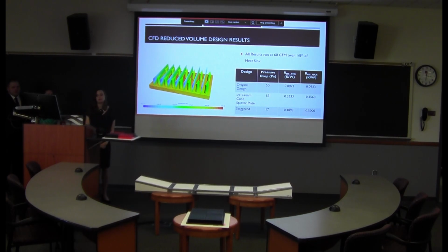Moving on to some of our results from the reduced volume designs. Again, all of these simulations were run at 60 CFM over an 8th of the heatsink. And as you can see, even though the staggered designs produced a slightly lower pressure drop than the inline design, our team decided based on these results that the inline would be optimal given that its resistance and thermal performance was better than the staggered design.